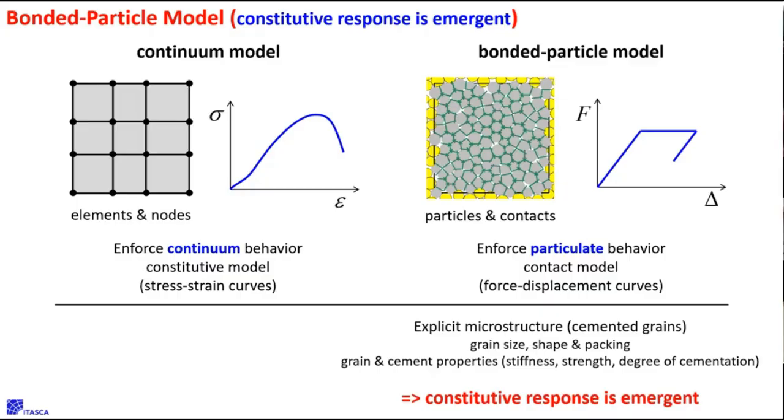Like the people at Itasca are doing state-of-the-art rock mechanics simulations. They're not working at laboratory scale. They're looking at real problems that are at excavation or above scale. And so they have to do things to reduce the properties they put in. Like the Young's modulus they put into a continuum model is a lot less than the Young's modulus that someone measures in an intact sample. And that's all I'm going to say at this stage. It's an open question, so there is no simple answer.